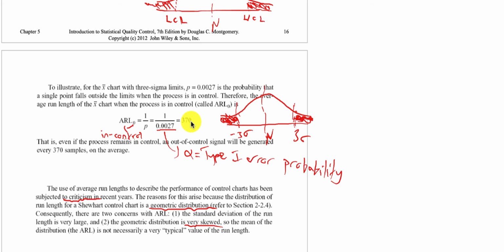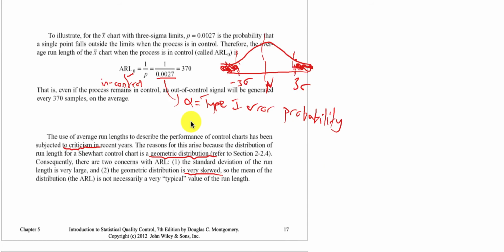These result from common causes, but they are there. And we expect that these out of control points will occur every 370 samples. This is the expected number. It can be after 2 samples, for example, but in average it is 370. We expect these numbers for in control processes.